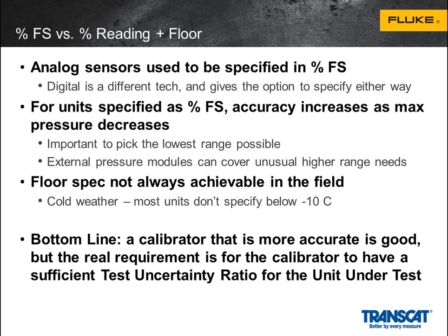So what's the bottom line? Basically, the calibrator, it's accurate. The more accurate and precise it is, the better it is. But the real requirement actually relates to how accurate your calibrator is compared to the transmitter that you're trying to calibrate. We're going to talk quite a bit about this here in a few minutes, but just keep in mind that raw accuracy isn't enough. It's the relative accuracy between your calibrator and the unit under test that really, really matters.